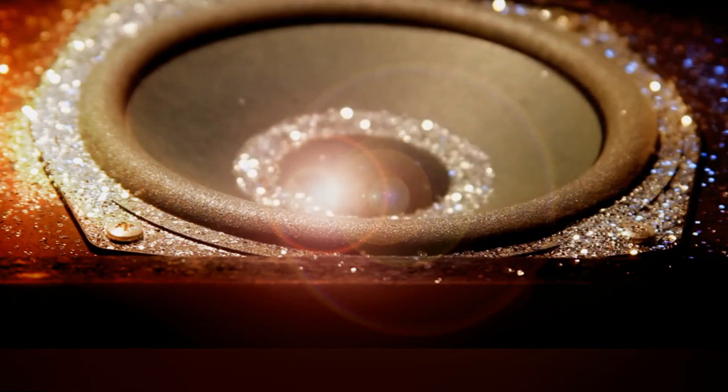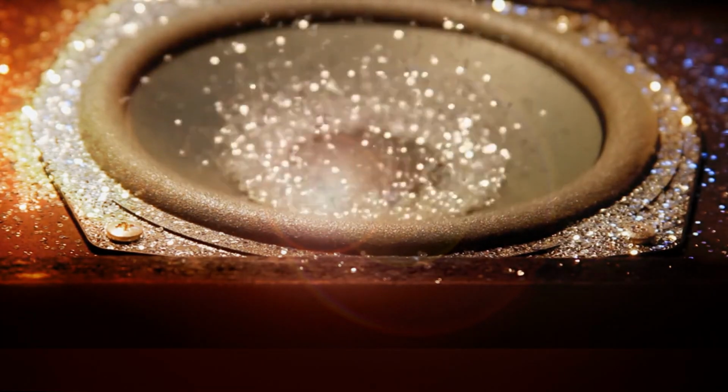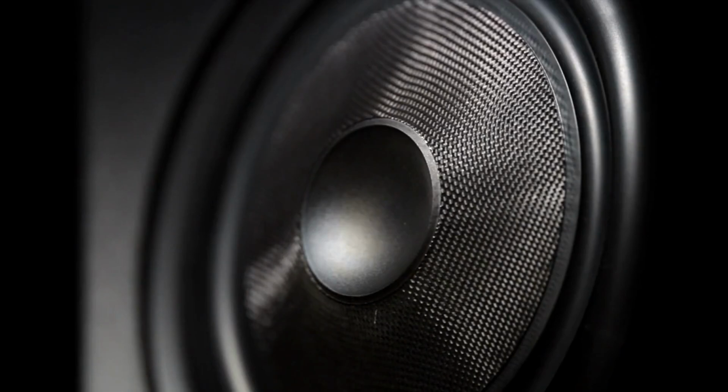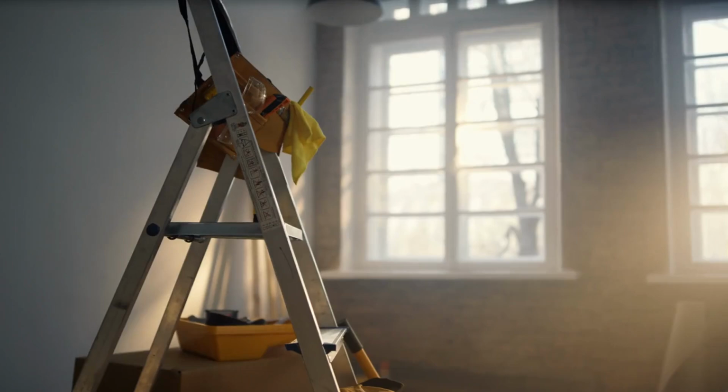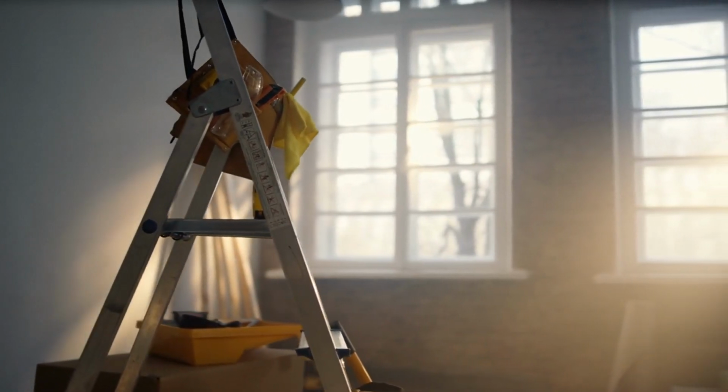Bass trapping. Bass traps are designed to absorb low frequencies that tend to accumulate in the corners of a room. Proper bass trapping is crucial for achieving a balanced low end in recordings. Choosing the right materials. When selecting materials for acoustic treatment, it's important to consider the specific needs of the room.